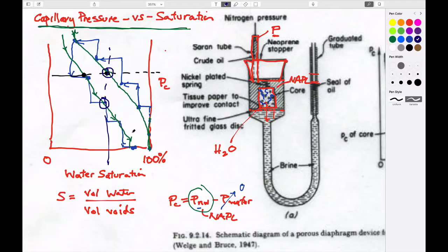All of the things that we'd like to know about this system are really controlled in this given experiment. So we can think about the value of the capillaries and the fractures in defining what the physics are of what's going on, but if we ever want to know what the saturations are in a system like this, then we can use these capillary pressure versus saturation curves merely by taking a sample of the soil or the rock and doing this kind of experiment to it.